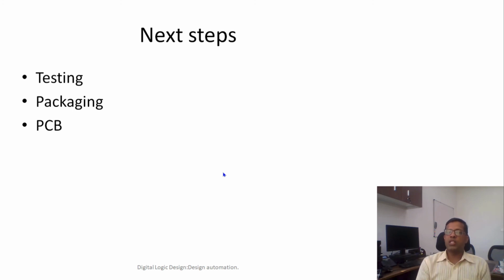The testing is done; this is also called validation and testing. Once it is verified that the chip is correct, people will package it, in a ceramic package, or a plastic package, or different kinds of packages, so that they can minimize the heat. Finally it would be placed onto a printed circuit board so that it can connect to other such chips. PCB designing comes even later, once a chip is designed. This is the overall process of ASIC design.